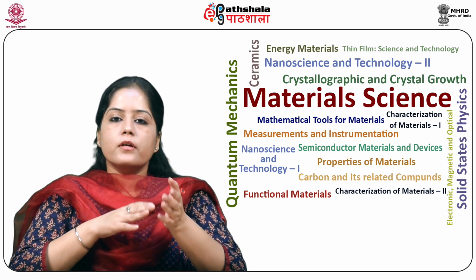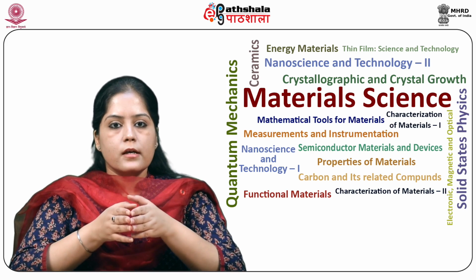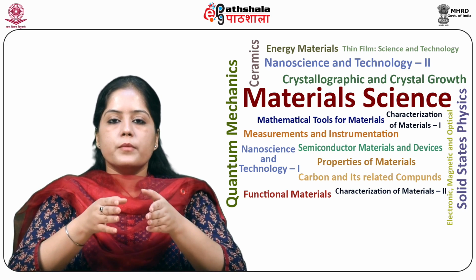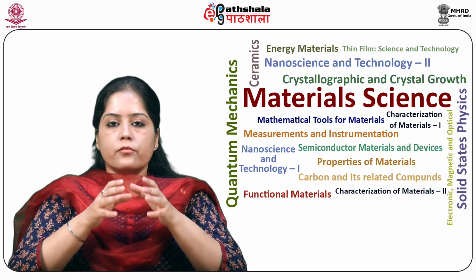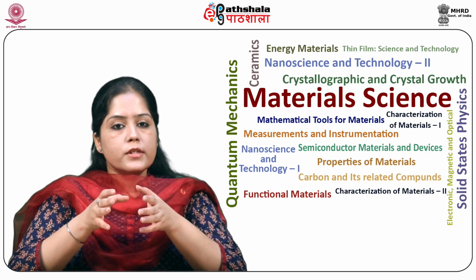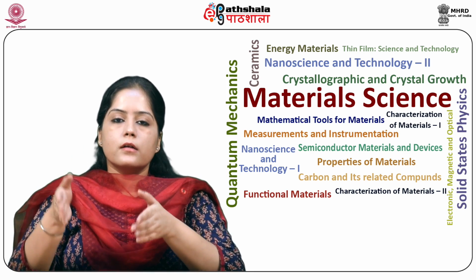Like its bipolar counterpart, the FET is a three-terminal device in which the current through two terminals is controlled at the third. Unlike the BJT, however, field effect transistors are controlled by a voltage at the third terminal rather than by a current.